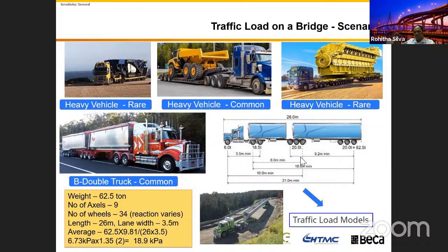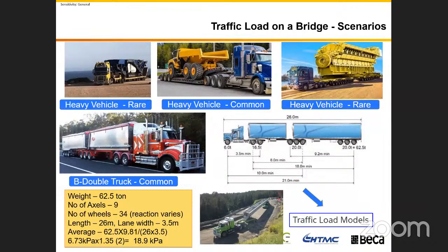We can put this in our grillage model, and we can run these in close spacing within legal limits, as close as possible, run along the bridge, and see the impact on the bridge. We can compare the same thing against the M1600 or LM1 load in the Eurocode. Yeah, we can verify the bridges like that.